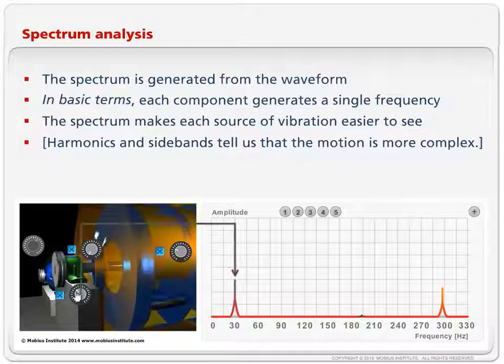And if I was watching this machine every 30 days, I'm doing tests according to the PF interval. It's understanding the failure modes to say, well, how quickly does the condition degrade? I've got to make sure that I get at least 2 measurements in the time where it's going from healthy to the time where it is functionally failed, where we are being forced, either because it's catastrophically failed or it's just unable to perform its function. We want to take enough measurements to detect that.